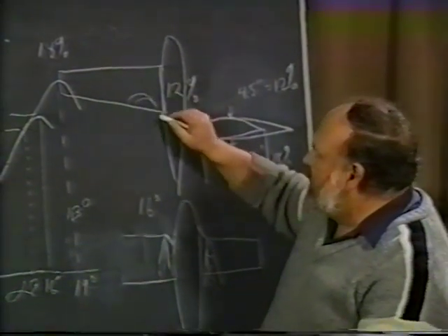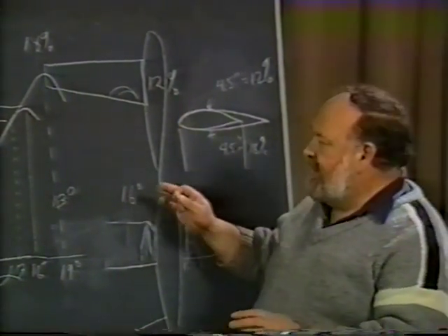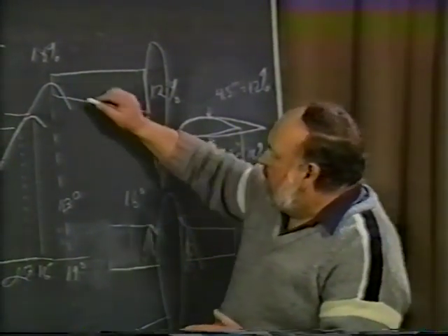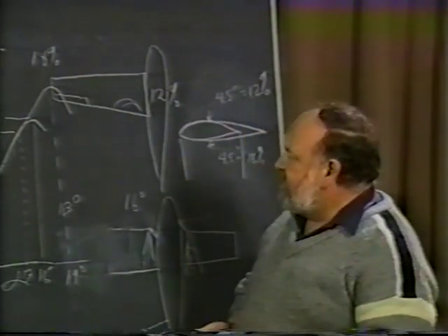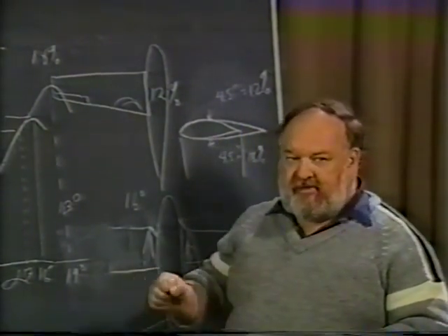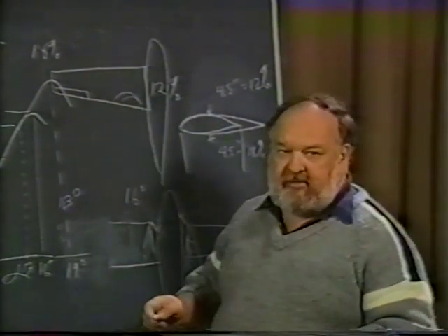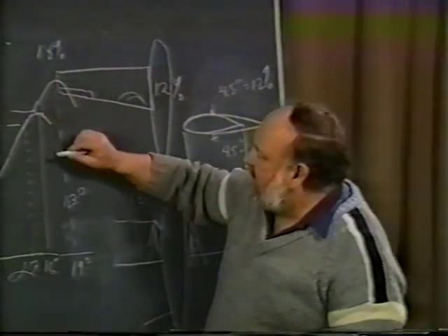The inboard section is going to start separating first. You're going to feel it on the tail. So you have beautiful stall warning characteristics. But more important is the fact that with the ailerons in the outboard section, if the pilot happens to put in some roll control, if he deflects the aileron downward here to lift that wing up, he is operating in this region right here.